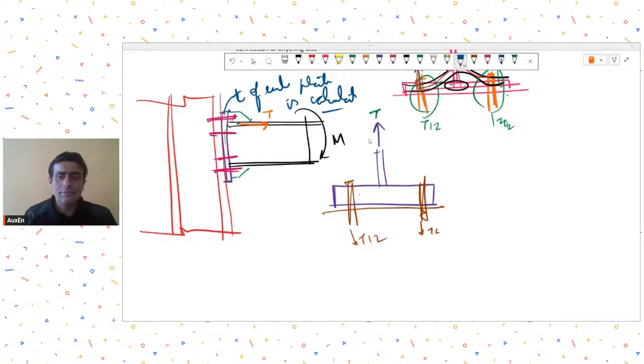And again, as I'm saying, in most of the connection designs that we do, we won't separately check for prying. The strategy that we adopt is that I will provide stiff enough thickness so that prying will not be a problem for me. Understood? Okay. So this was engineer Charan with his query.